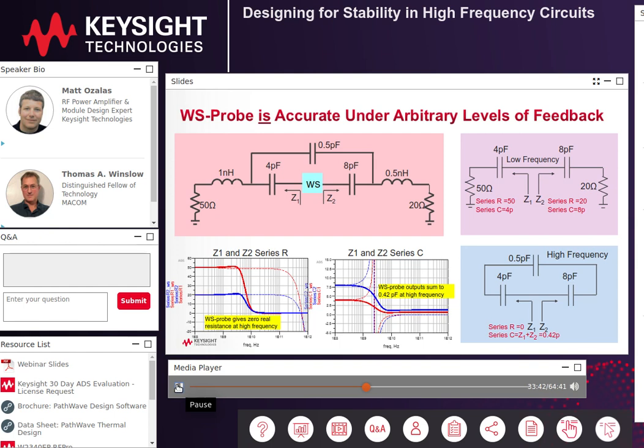The new WS probe analyzes the network that it is embedded within, and it does a network reduction and accurately decomposes the loop impedance. Now, how it does this is beyond the scope of this webinar, but this net loop impedance that it calculates behaves exactly like the 3 series capacitances that sum up to a total of 0.42 picofarads. The probe can calculate, again, this is beyond the scope of the webinar, but it can calculate the equivalent bidirectional looking impedances, the sum of which must be equal to the total loop impedance.